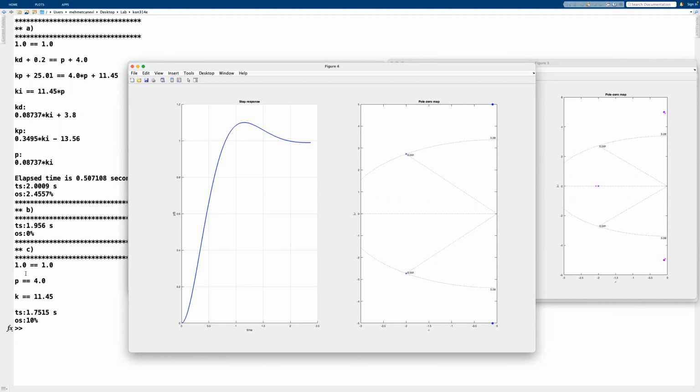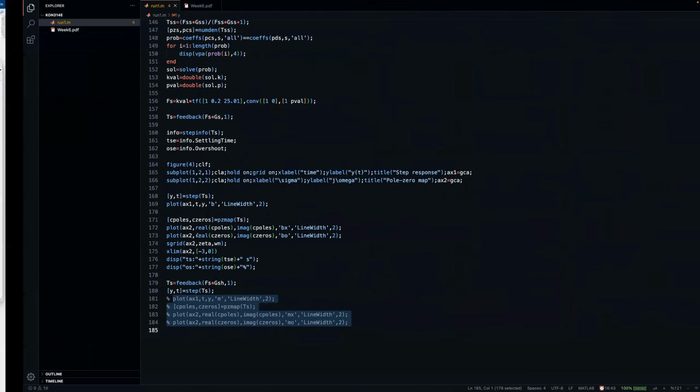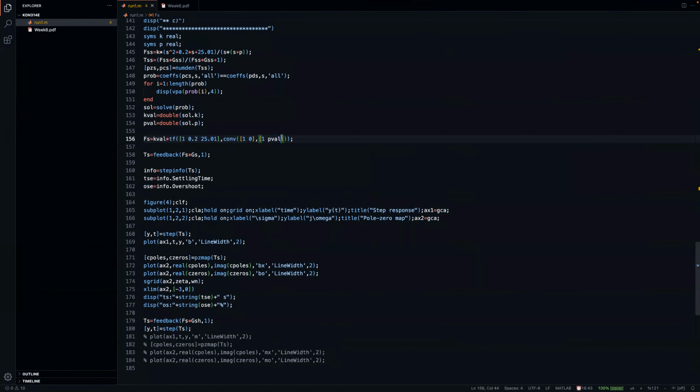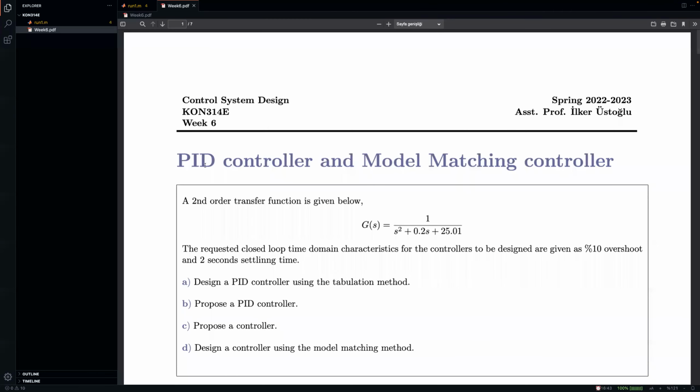And we can see on the left half, we have 1, P, and K, which is basically the characteristic polynomial, and on the right half, we have PDS, and we've just chosen P and K accordingly. So we kind of propose this controller, which is a second order controller, but has a pole zero cancellation, and it just basically gets rid of the poles of the original system, and places some poles so that it gets the job done here.